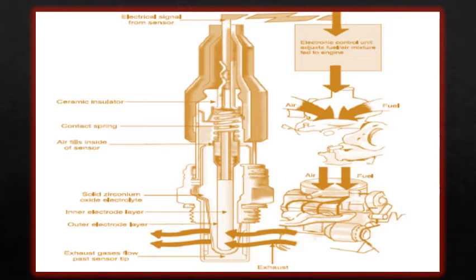Electronic ignition. Development of electronic fuel supply and ignition control has been given an extra boost by the introduction of strict laws governing the amount of polluting gases that may be present in the exhaust. The limit can be met only by controlling ignition timing and fuel delivery far more accurately than had previously been the case. Many cars now have electronic ignition, although most are still timed mechanically.